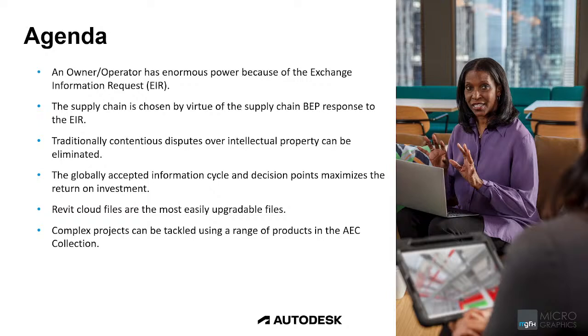So you could include further clauses to state, if you do overstep the boundaries, you open yourself to litigation. Then you will be taken to court if you steal other people's intellectual property. Or you could try to protect the individual consultants on the project and state, we will accept that you share Industry Foundation Class (IFC) or NWD files with the other consultants if you are concerned about that, because then the models that you share are static. However, the originally authored file will still be available to the owner or to the appointing party.